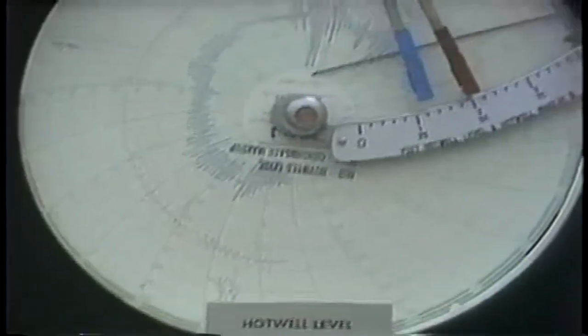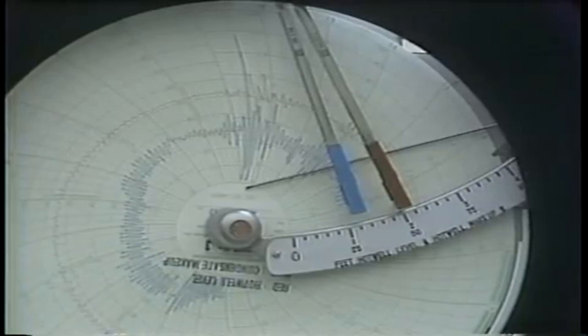drum level. The operator in this case has three choices of action to take. If it is possible to get to the isolation valves, the gauge glass can be taken out of service and repaired. However, if the leak is severe enough, the escaping steam may make it unsafe for personnel to attempt to isolate the gauge glass. If this is the case, the operator may be able to maintain the proper level in the boiler drum by increasing the make-up water rate.